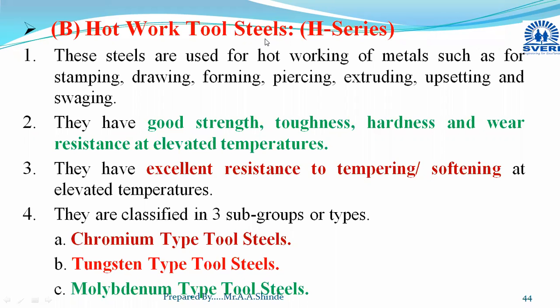Okay, why are they able to provide these properties? Because they will provide you excellent resistance to tempering or softening at elevated temperatures. At higher temperatures also they will give you hardness. They do not become soft because tempering does not occur here. Hence they will remain hard and provide very good wear resistance at higher temperatures also.